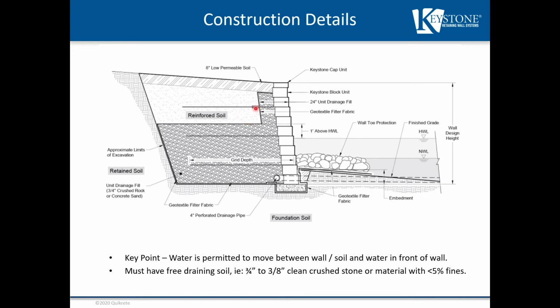The filter fabric is the key element here as well, especially as well as the leveling pad, which we're going to talk a little bit about here. We're going to have a fabric that's wrapped and protected the toe and base of the leveling pad. The leveling pad could be gravel, must be wrapped in filter fabric, or concrete. And if it's concrete, we don't necessarily need to have the fabric, but we need to have the fabric that will come and wrap along the face with erosion protection.